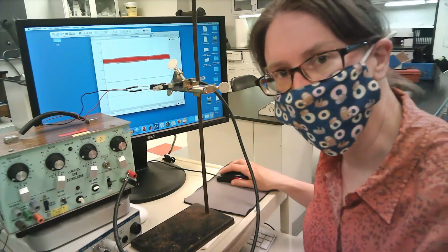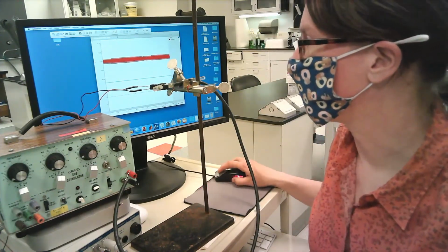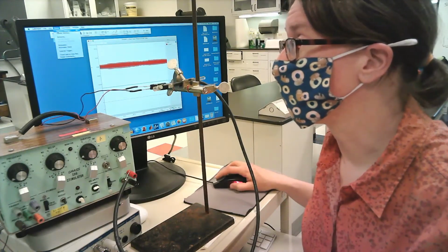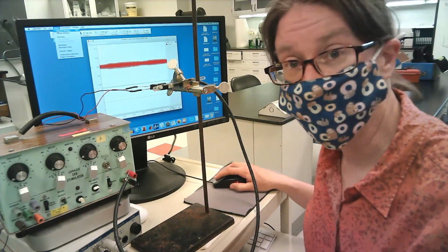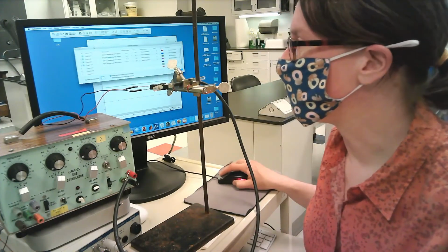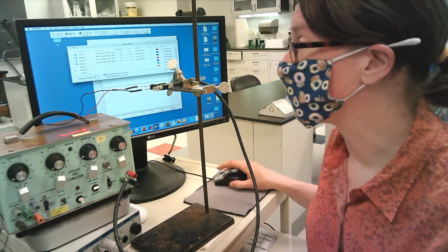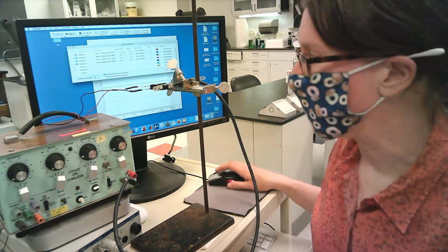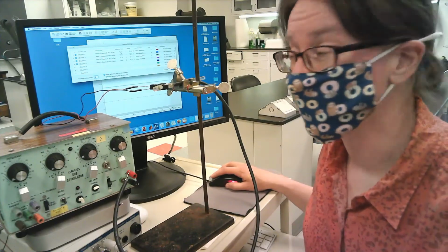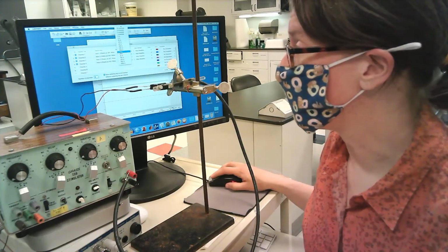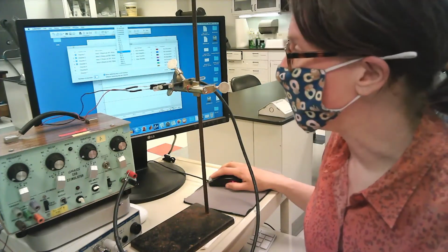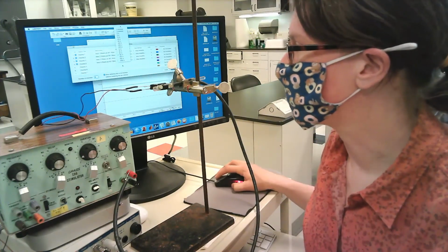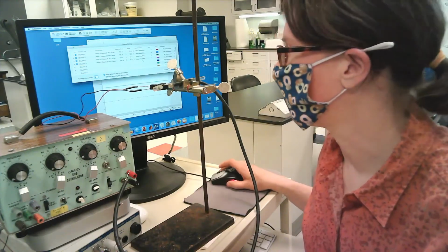So for doing that, I'm going to stop the recording I have going currently, and I'm going to go up to the setup window, and I'm going to select channel settings, and this is going to bring up some setup conditions across the different channels. You'll notice one that is a drop-down menu for the sampling rate. And so for this, what you're going to select is 10,000 samples per second. And that's going to change across all of your recording channels.